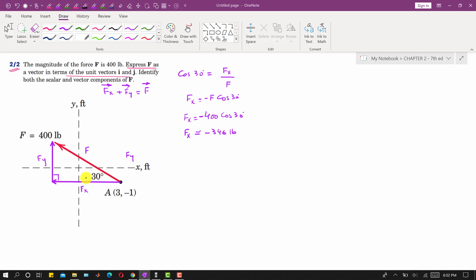So now you need to remember that whenever the given force is making angle with f of x, then f of x will be the cos component, right? So from now onwards we will use f of x directly as f cos of 30 degrees, right? And similarly f of y will be the sine component, right? So f of y is f sine of 30 degrees, and it is acting in the positive y direction, so we have to write plus, right?